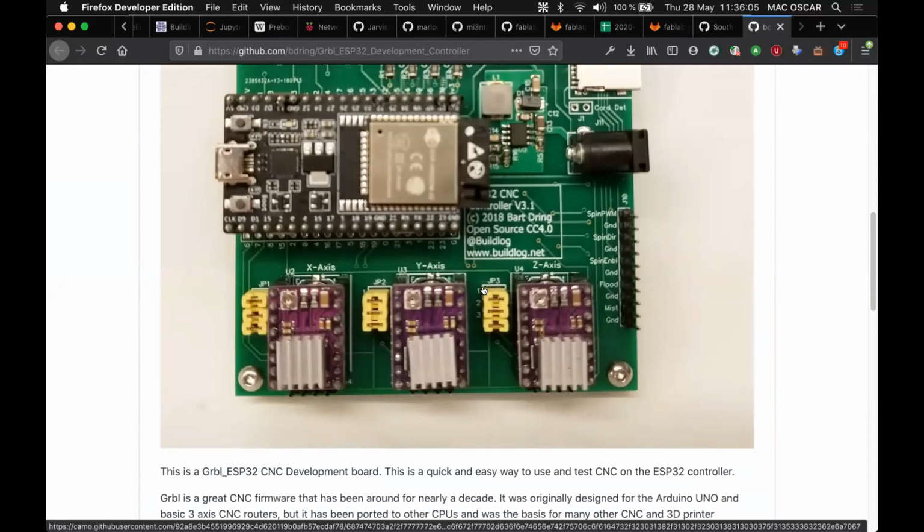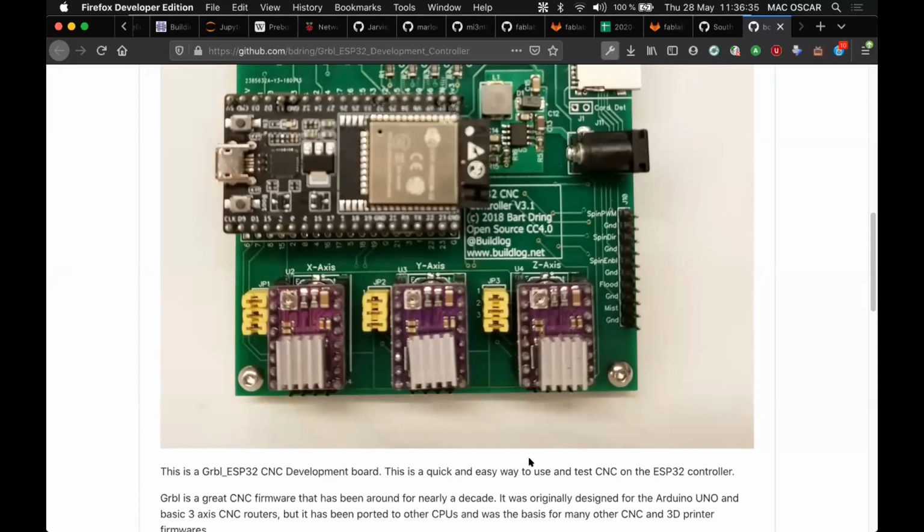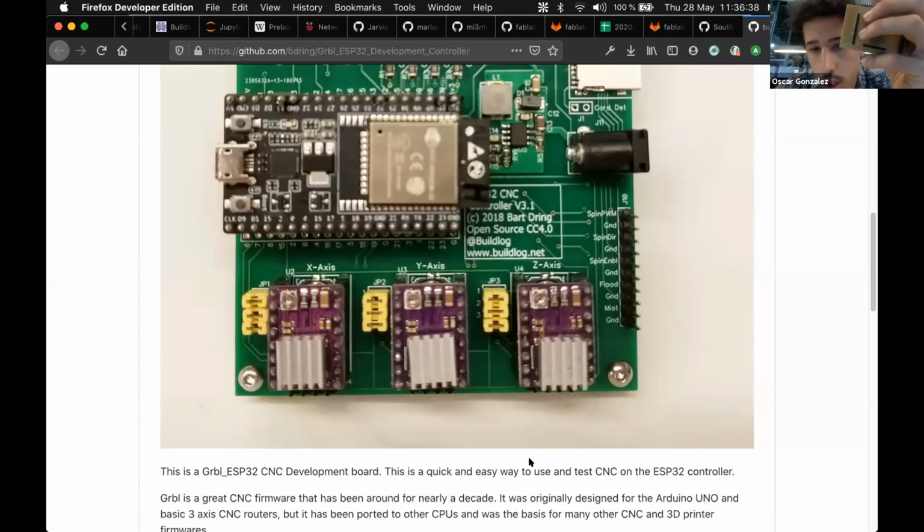Basically, you are making a short between them with an external, let's say, what we call a bridge. And these are removable so that you can put them or not based on some configurations. And that's what we are doing in here. So you are outputting always through the PWM, but if you want to select the MOSFET, you just put the bridge in there and don't output through the 5 volts PWM. Basically a way to select how to route your circuit with external hardware, let's say.